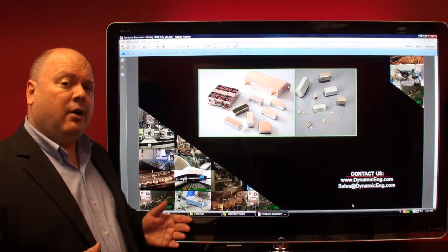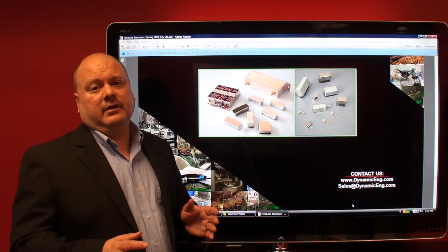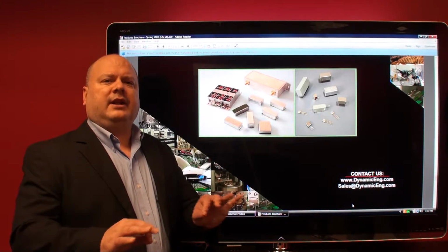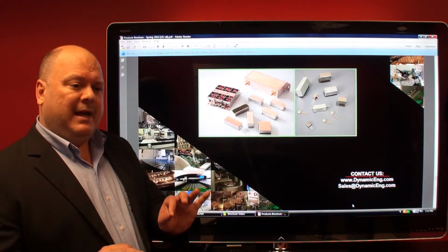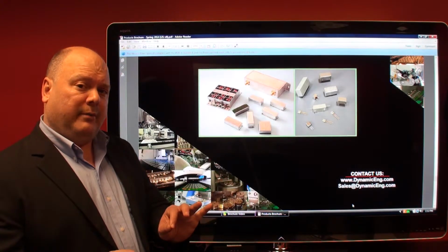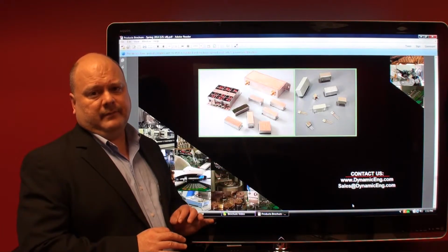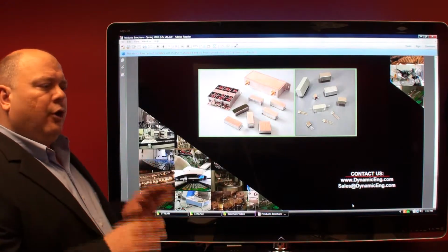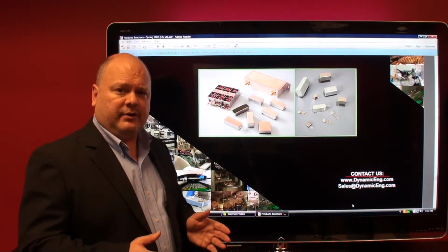You may not bring all those nonlinear properties out at 25 degrees C. So you might be measuring the crystal parameters at room and everything looks good. But if you overdrive the crystal, maybe the nonlinearity in performance shows up in some of the crystal parameters over operating temperature. Now for LC filters, there's no crystals inside, so you can drive to very high powers.